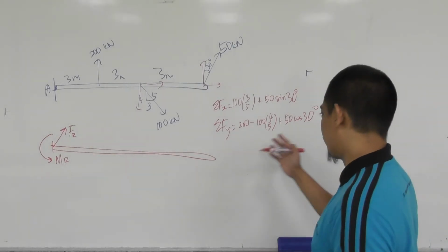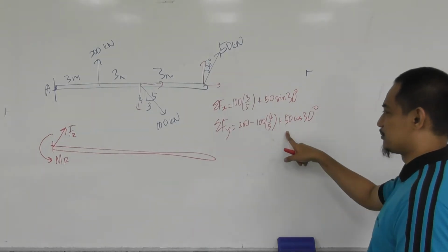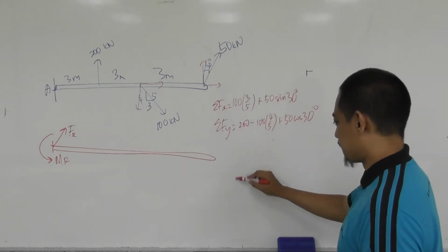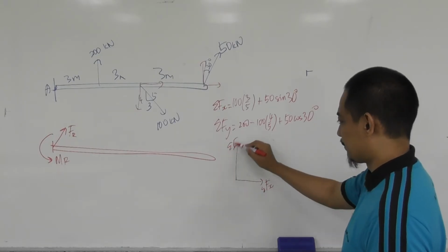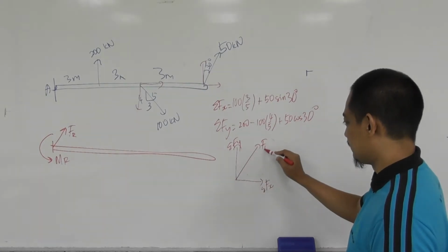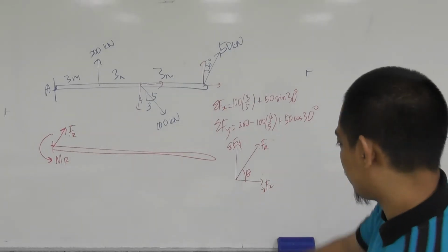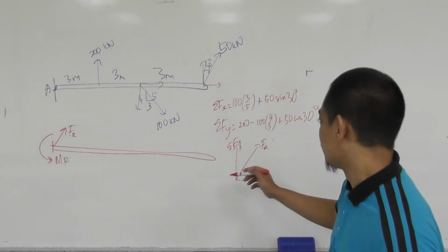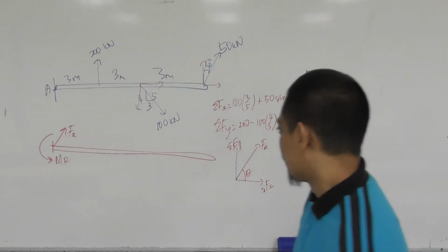Regardless of the value, whatever the value that you have, for example, this one tends to be positive, is it? Let's assume this is positive, and this is also positive, meaning that summation of Fx and summation of Fy are in this direction. If that is the case, then FR is indeed here with a theta there. Right, so your answer should carry all of that information. Right, and I believe you know how to calculate this one already from whatever given data there. Right, what about MR?